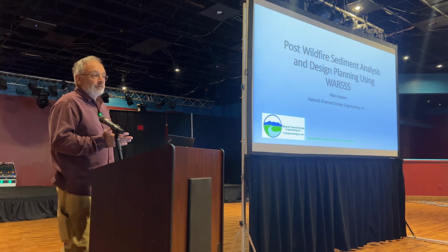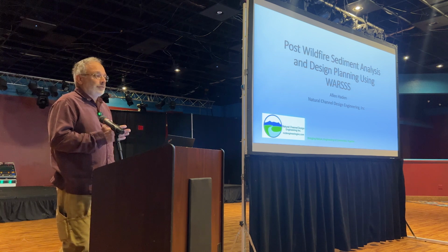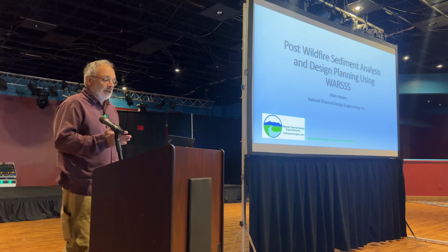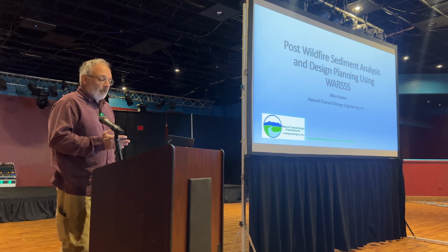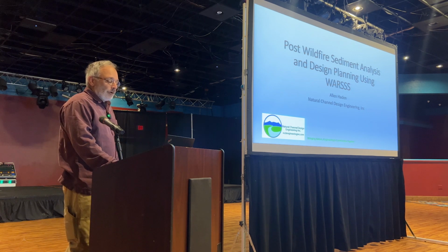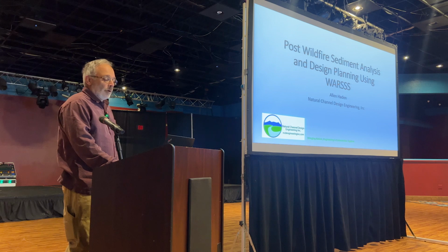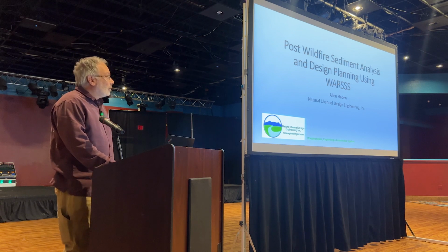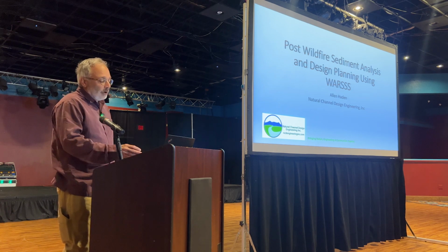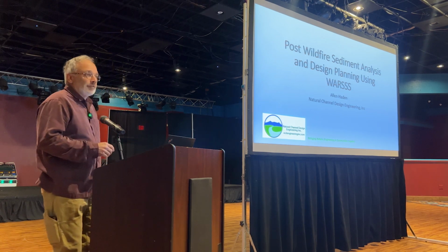Some of these that we've been asked to work on actually affect the urban wildland interface, a lot of houses, a lot of infrastructure, and a whole other realm of panic, if you will. So there's a lot of hurry involved in this, and so the tool that we rely upon to do a lot of this assessment is this WARSSS methodology. WARSSS is the acronym, and it stands for Watershed Assessment of River Stability and Sediment Sources. It was developed by Dave Rosgen and his cohorts at Wildland Hydrology.